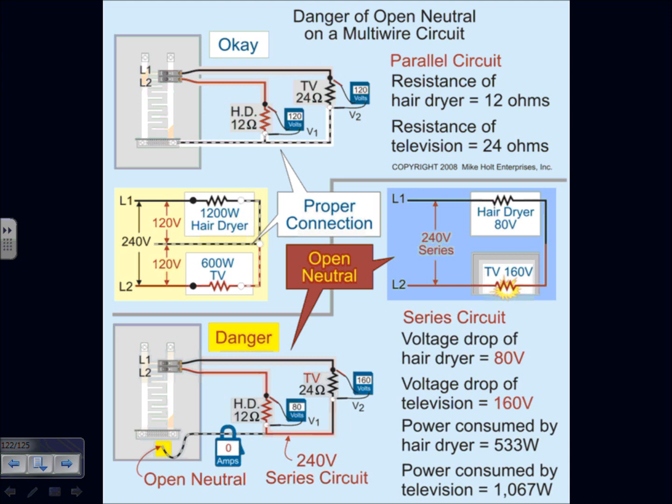At the end of the day, I just want to get it done, and I work when things are hot. The first thing, when you tie to a circuit hot, which you shouldn't do, you should turn everything off and tie it. But if you are to do it, you put the ground to ground first. You ground the system. The second thing I always do is the neutral. The last thing, because you're tying things hot, remember, you're going to be very careful, is you tie the hot to the hot.